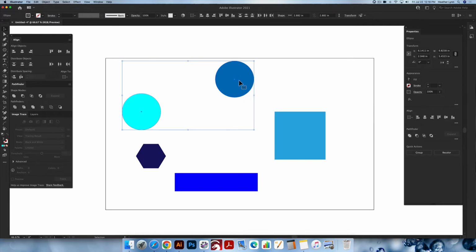If you then select this again, one more click, so let's do this one so you can see it. Click, see how it turns into a bold blue outline? Now when you center, it's going to jump over. It will no longer pay attention to this rectangle, which is the bounding box. It's going to be focused on this. So if I want this to jump over and line to the left, it will.